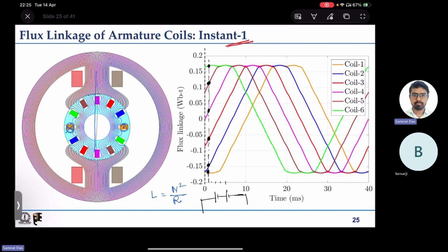So this will form one of the parallel paths, and the other one will be something like this. Again, the third coil will be shorted, so this will become the equivalent circuit of the armature. Again you will find two coils in series with non-zero EMF which will get added. So you will have 200 volts if in one coil the voltage is 100 volt.